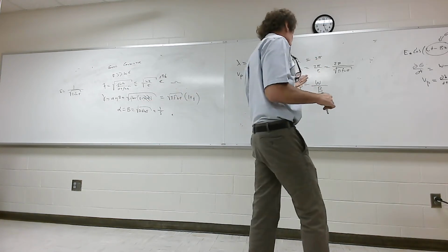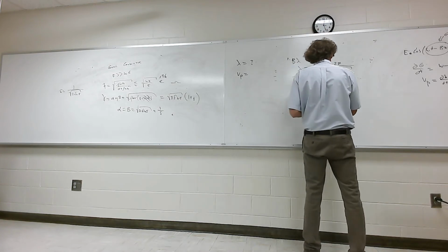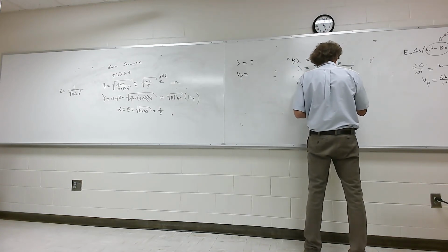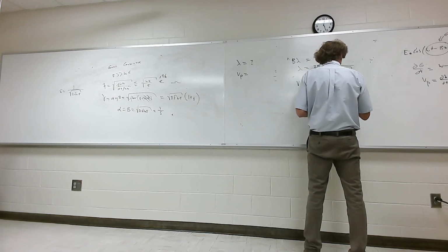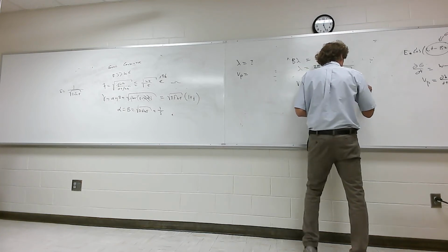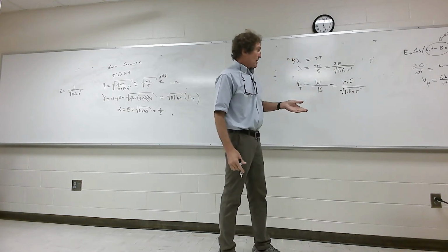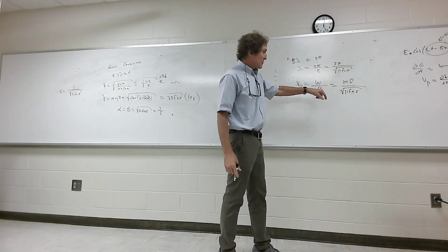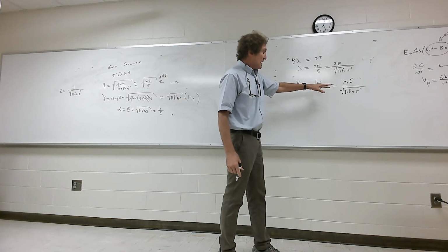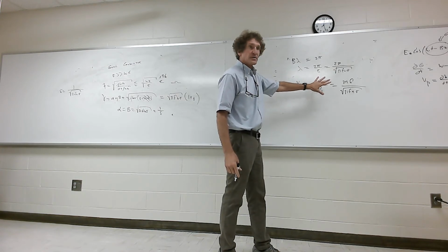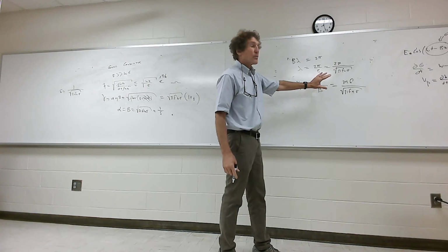So for phase velocity, here's where it gets weird. Omega is 2 pi f, right? And then we put down beta, and beta is square root of pi f mu sigma. Now we can go ahead and put square root of f on top, and we can put square root of pi on top, and make that 2 a 4, and put mu sigma on the bottom. We can do a bunch of stuff to modify that into a form you like.